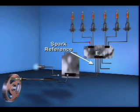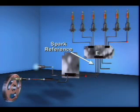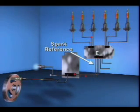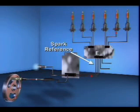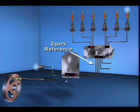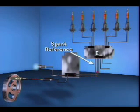The spark reference signal is a signal from the ECM to the ICM. The spark reference signal indicates to the ICM that cylinder number 1 is next in the firing order and commands the ICM in and out of multiple spark discharge mode. The multiple spark mode of operation will be discussed later in this section. The ECM receives the input for this signal from the engine position sensor and the 7th protrusion on the camshaft gear. There is 1 spark reference signal for each 6 spark timing signals.